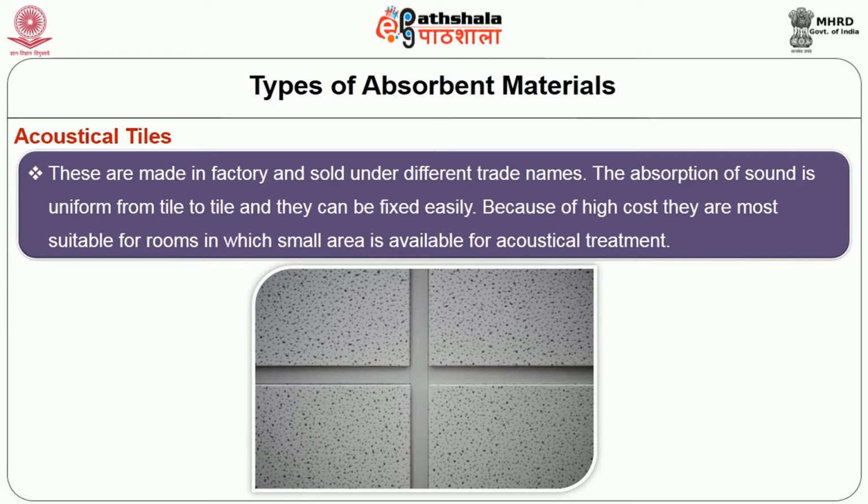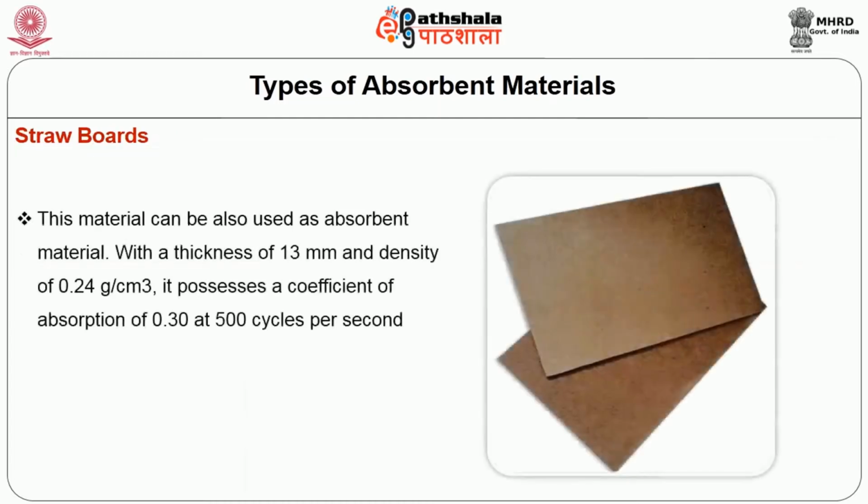Acoustical tiles are made in factories and sold under different trade names. The absorption of sound is uniform from tile to tile and they can be fixed easily. Because of high cost, they are most suitable for rooms in which a small area is available for acoustical treatment.